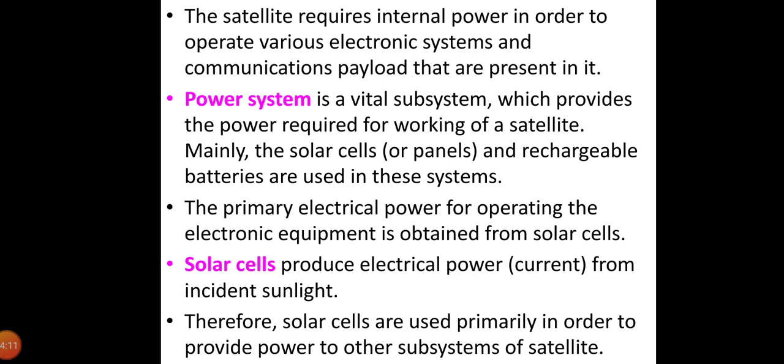During the launch sequence, the outer cylinder is telescoped over the inner one to reduce the overall length. Only the outer panel generates electrical power during this phase. In geostationary orbit, the telescoped panel is fully extended so that both are exposed to sunlight. At the beginning of life, the panel produces 940 watts DC power, which may drop to 760 watts at the end of 10 years. During eclipse, the power is provided by two nickel-cadmium long-life batteries which will deliver 830 watts. At the end of life, the battery recharge time is less than 60 hours.